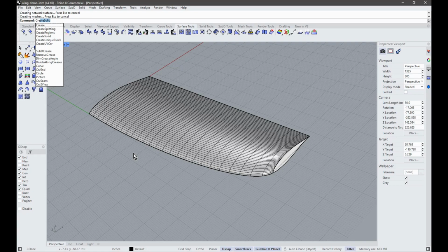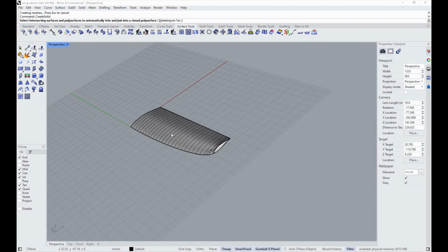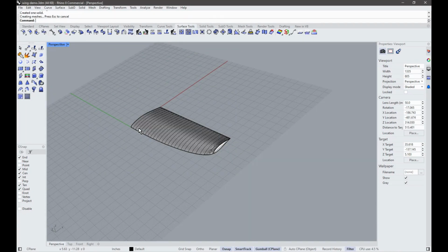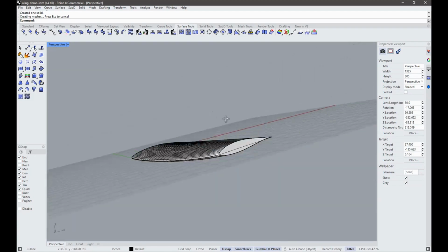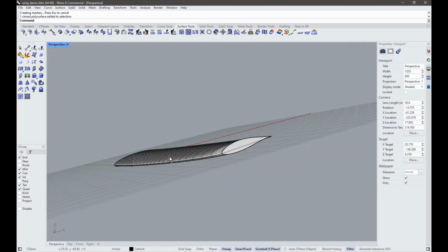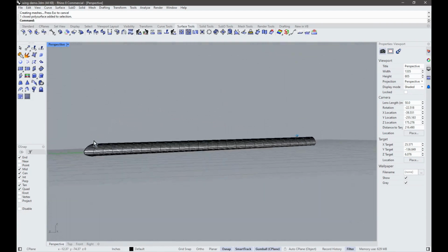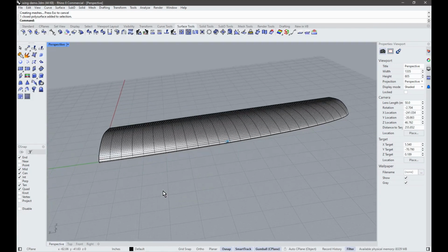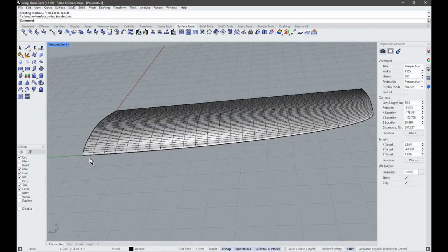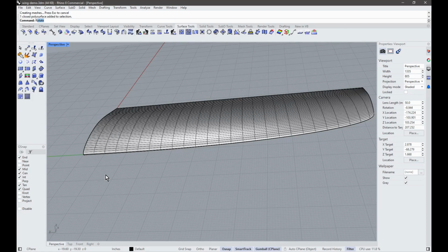And that's the command right there, create solid. Highlight everything. And now this should be seen as an actual solid object. If you want to go 3D print this or send it off to something that's solids, you can work with surfaces. Now this is all done flat, but if say you want to get dihedral on this thing, do another rotate, say 3 degrees of dihedral, rotate.